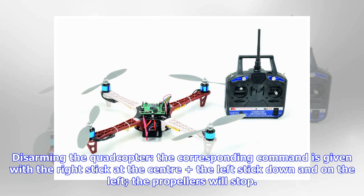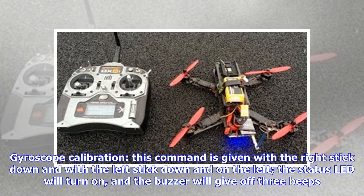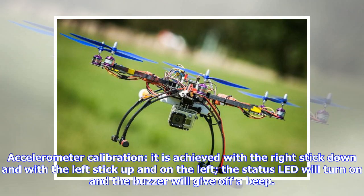Disarming the quadcopter. The corresponding command is given with the right stick at the center, the left stick down, and on the left, the propellers will stop. Gyroscope calibration. This command is given with the right stick down and with the left stick down, and on the left, the status LED will turn on, and the buzzer will give off 3 beeps.